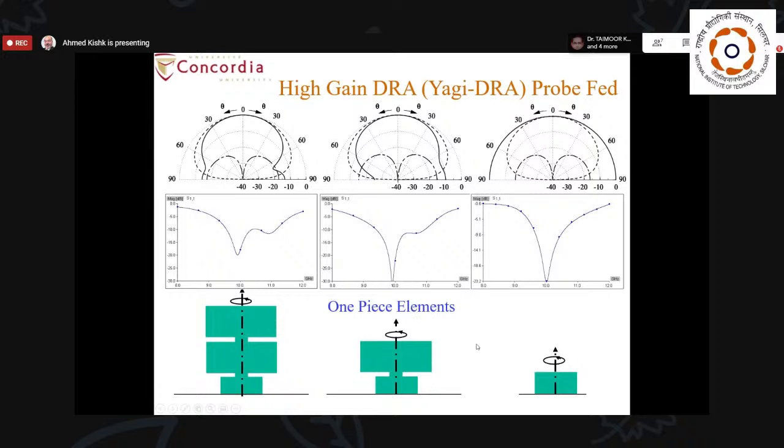And by doing this, you can see that this resonator has a similar frequency as such, but we need another one acting with a close resonant frequency to the resonant frequency of this. So when you have it on top, you'll find that this also interacts with the ground plane. So there are some fringing fields coming here. That means that the effective permittivity is smaller. That means the size has to be larger to operate at the same resonant frequency. And that's the reason why the upper dielectric resonator is larger than the lower one.